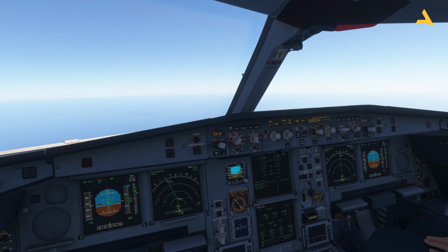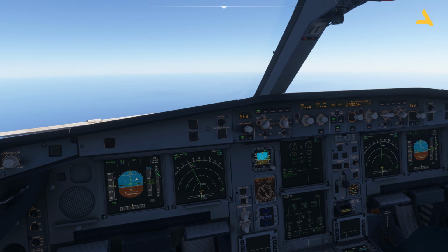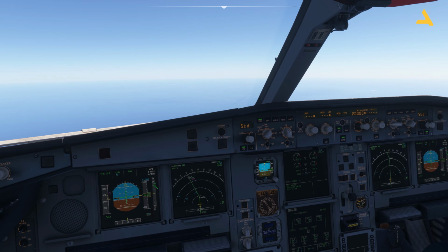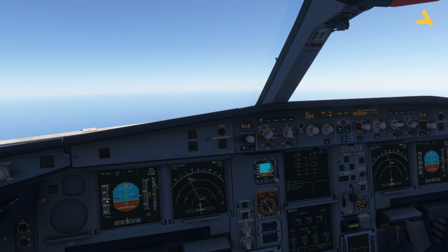Now you can see that the plane is aiming for 305 knots, and the vertical speed is now 1,100 feet per minute. That's it. Now you can also adjust the speed. Right now it's in the manage mode. You can bring your cursor, and as soon as you see the down arrow, you can go into the selected mode. So let's say if I reduce the speed, now you can see that the speed will reduce, and the climb rate has increased.